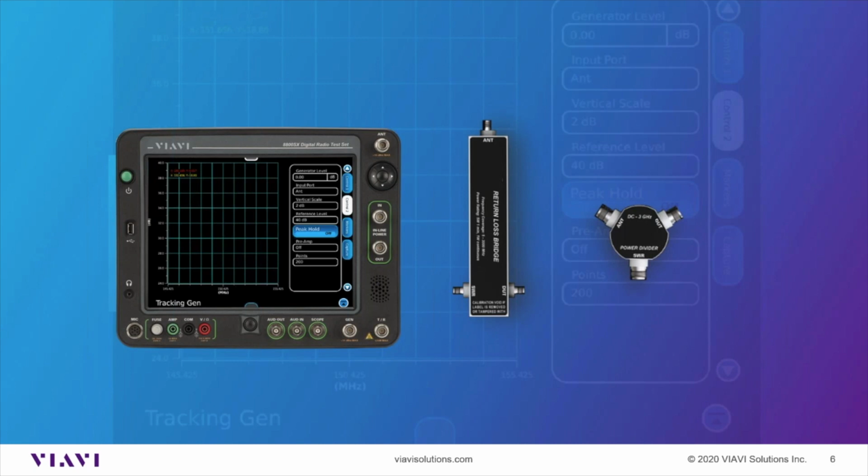It's going to be on frequency. You just put the frequency in, and it automatically is calibrated to that frequency. There's no slugs to turn around or forget in the shop, and that's something that's kind of unique to the 8800SX. You don't have that built-in inline power meter in other service monitors.